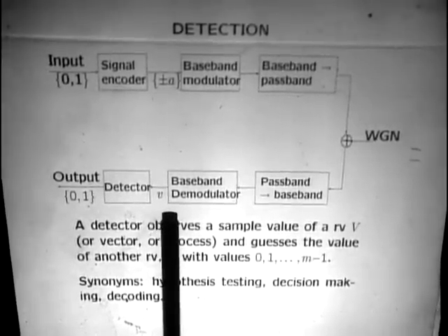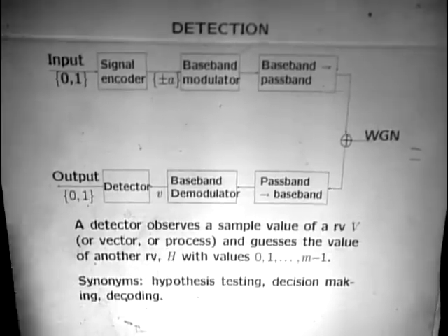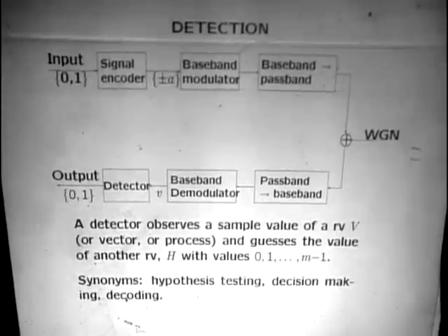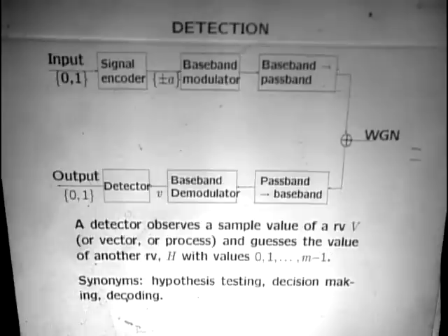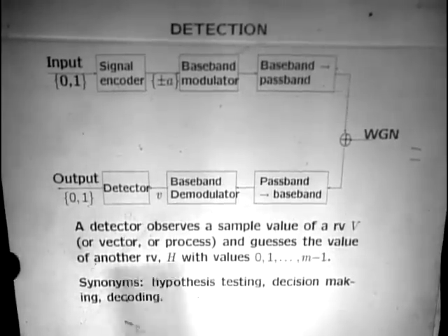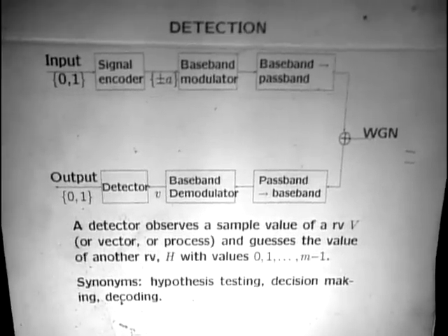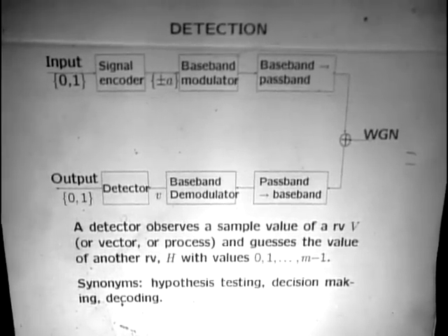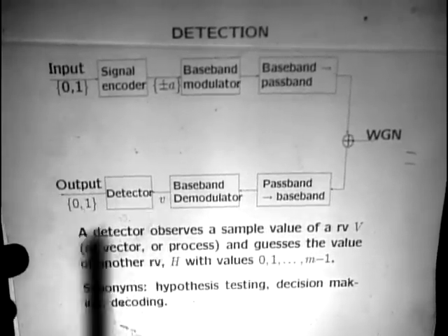One is that a 0 was sent, and the other that a 1 was sent. And on the basis of this observation, you take first the hypothesis 0, and you say, is this a reasonable hypothesis? Then you look at the hypothesis 1, say, is this a reasonable hypothesis? And then you guess whether you think 0 is more likely or 1 is more likely, given this observation that you have.